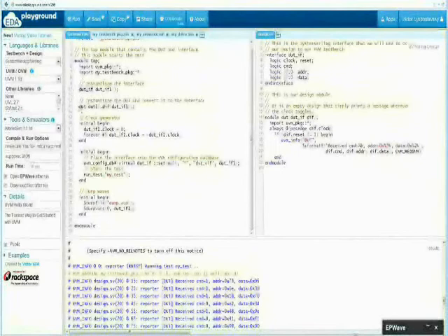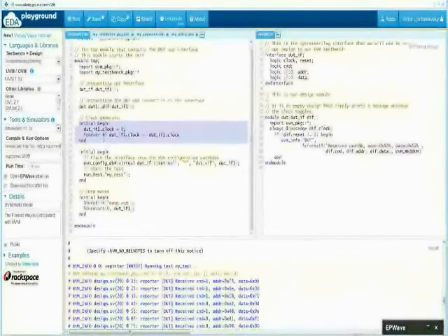On this software verification model, interface design under test, we use the interface to drive the clock directly from the top level. The virtual interface comes into play, and the virtual interface becomes a pointer and puts it into the UVM config database.